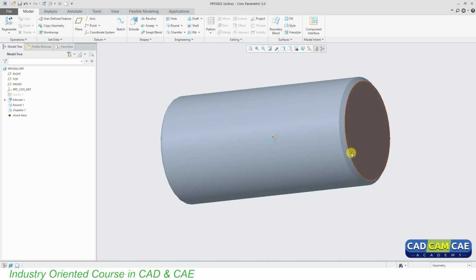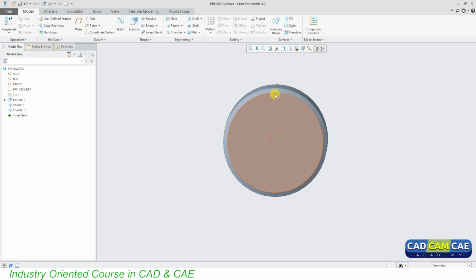So the pattern option means, let's say in this particular surface you need to create circumferential holes for bolting the side plate on this surface. Let's say you need 12 such threaded holes, so that you can put the plate and then bolt it from the outside. This pattern option will be very useful in these circumstances, wherein you need to repeat a certain feature after a certain angular distance, all over the circumference. That is how patterning will be helpful.